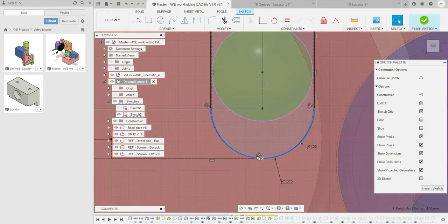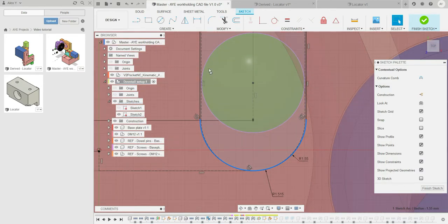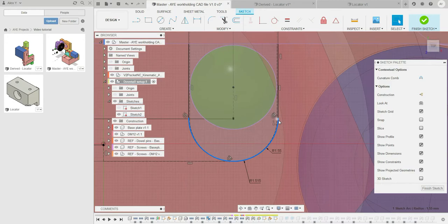It goes to the same depth, both are on the same tangent there, but it goes ever so slightly wider. That's to allow a little bit of extra room for this pin, because when I machined it on my machine, I found that the slot was just a little tight. So I increased the diameter of this curve and the width here to 3.1 rather than 3.03.